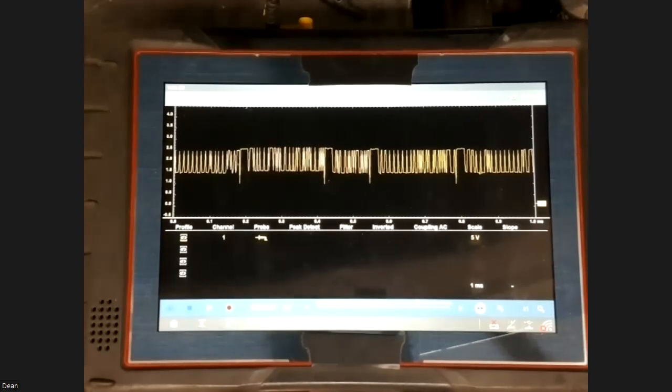Yeah, is this what you would call a normal signal then? This one here would be a normal signal. Absolutely. This is normal communication for the CAN low in a GM system. With a little bit of training and understanding, you can tell if this thing has a bad ground or a bad power, or if a module is starting to short out. You can actually do that.